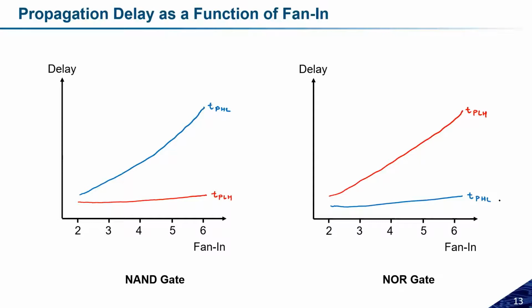Okay, and we need to optimize. So the important thing is, if I'm talking about the NAND gate, in that case I need to optimize the pull-down network if I have to get less propagation delay. So we have to do some exercise on the pull-down network so that we can have less delay. Similarly, if I'm designing the NOR gate, in that case I need to do some modification on the pull-up network side so that we can reduce the TPLH and get less propagation delay.